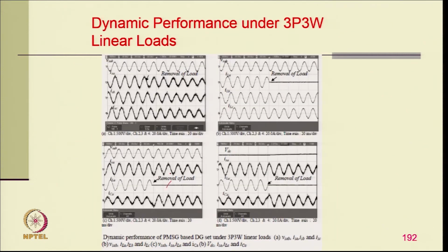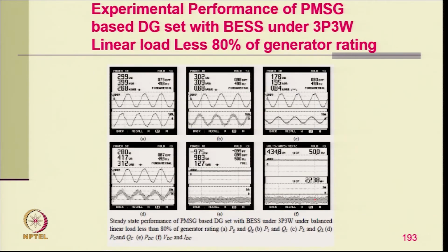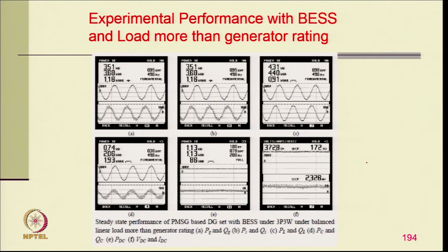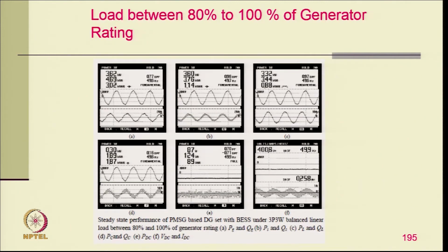And during dynamics, when load is unbalanced, generator currents are not disturbed, they remain sinusoidal and balanced, and the battery is getting charged or discharged according to the load. You can think about it, we are having even a generation typically fixed, but even if the load may be a little more than that, it is capable of feeding that condition also at varying load. So, you can generate more or less, but the battery will get automatically charged from that or compensation.